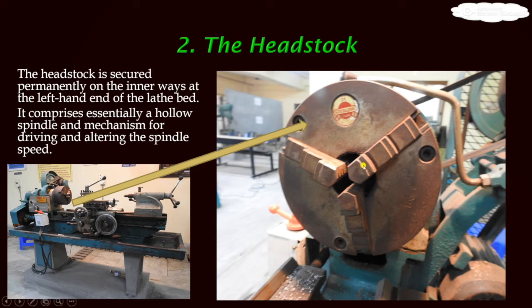And if we displace this particular jaw in the opposite direction, then simultaneously these two jaws will also move outward. Means individually or independently we can't control the jaws, and that's why a workpiece automatically gets its center, automatic alignment.